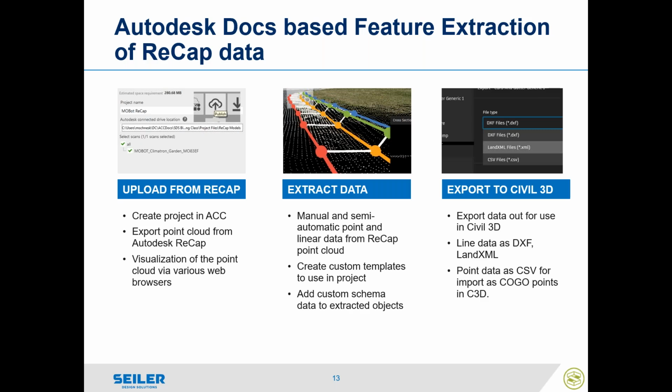So export to Civil 3D as line data as a DXF or LandXML. I've got a little caveat for the LandXML for those who have tried it and noticed something. I'm going to point that out. Point data as CSV for importing as COGO points in Civil 3D.